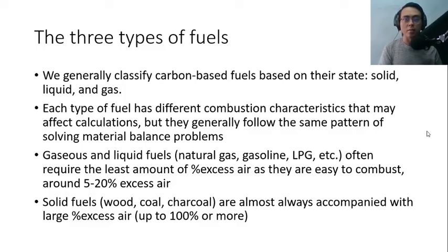So that's the main difference between the gaseous and liquid fuels and the solid fuels such as wood, coal, and charcoal. Wood, coal, charcoal, and other types of solid fuels are very hard to continuously combust because you need to grind them into very, very small particles for them to continue burning. You need to expose a larger surface area of the solid. They are almost always accompanied by a large percent excess of air, sometimes even more than 100%, because of the difficulty of sustaining complete combustion.